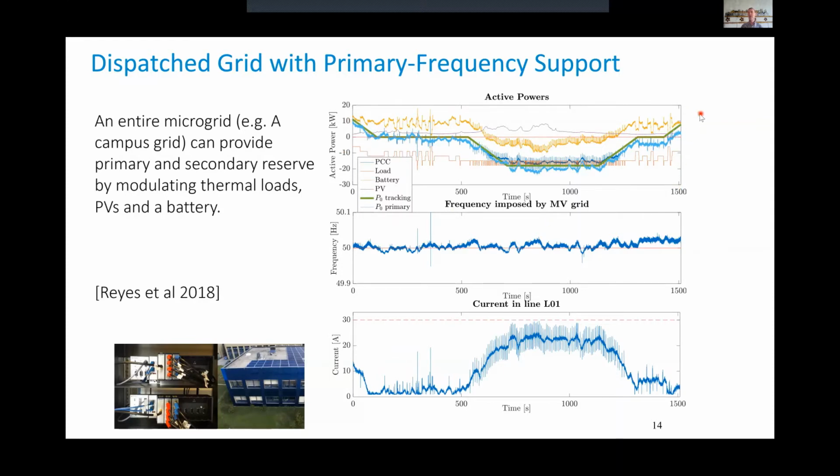The nuclear plants are replaced by distribution networks that produce the energy. So if they produce the energy, they should also participate in the stability of the system. In particular, it will be cheaper and more robust if they provide primary and secondary reserves. It's very easy to provide this reserve if you have produced a dispatch plan. If we know, for example, during this period of time, the expected power is 0, then we can define a regulation as a difference between 0 and what we produce.